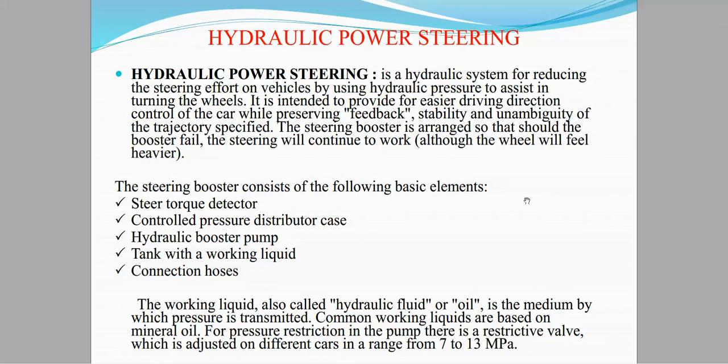The working liquid, also called hydraulic fluid, is the medium by which pressure is transmitted. Common working liquids are based on mineral oil. For pressure restriction in the pump, there is a restrictive valve which is adjusted on different cars in a range of 7 to 13 megapascal.